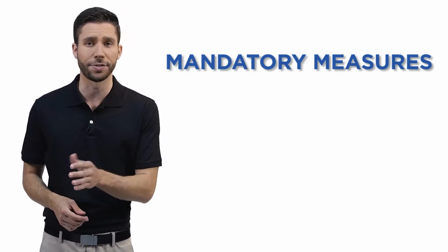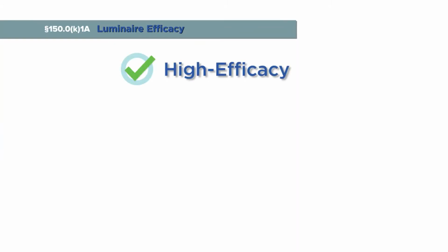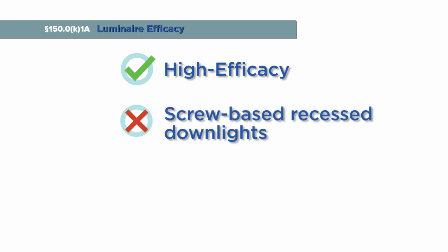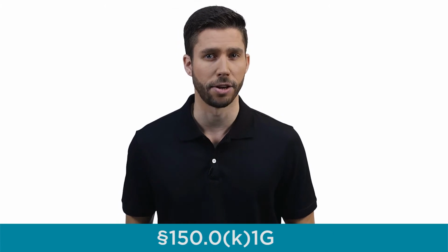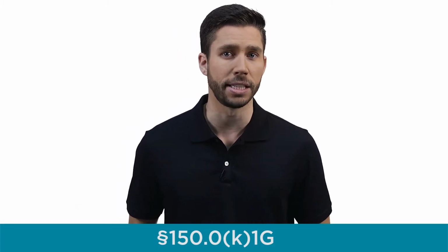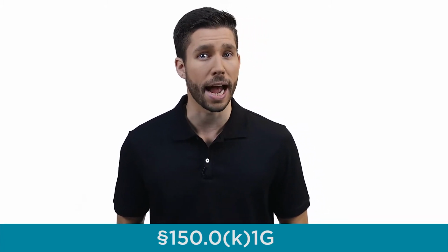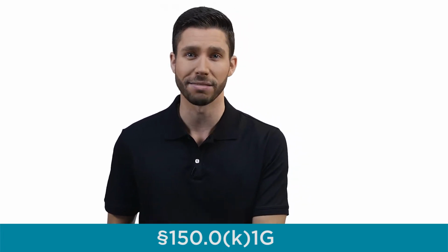Indoor and outdoor luminaires for new homes must be high efficacy. This is specified in Section 150.0(k)1A of the Energy Standards. Any luminaire except screw-based recessed downlights can be classified as high efficacy if the installed light source meets the requirements in Table 150.0-A. Under the 2016 Energy Standards, luminaires that utilize a screw-based socket, excluding hardwired ballasted HIDs, must contain lamps that comply with JA8 high efficacy requirements. Remember, screw-based ceiling recessed downlights can no longer be installed in California's residential buildings.